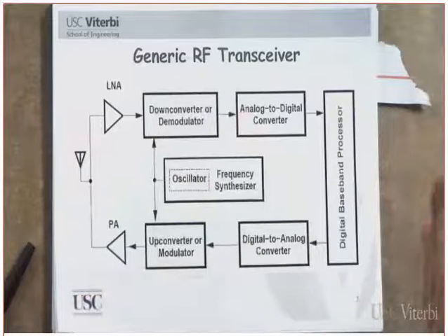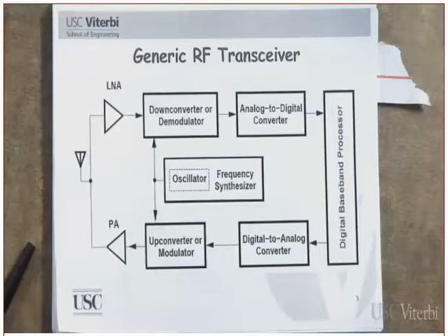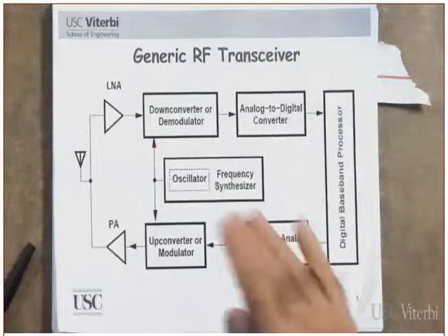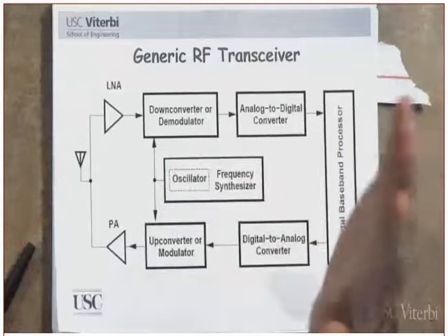We shape the pulse. For example, GSM uses a modulation technique that is called what? GMSK. And the G stands for what? The Gaussian shaped minimum shift keying. Do you know the Gaussian? How does it look like? Sharp edges or smooth edges? Smooth edges, which means what? Its spectrum will become what?